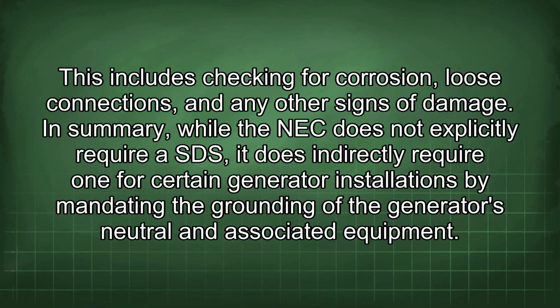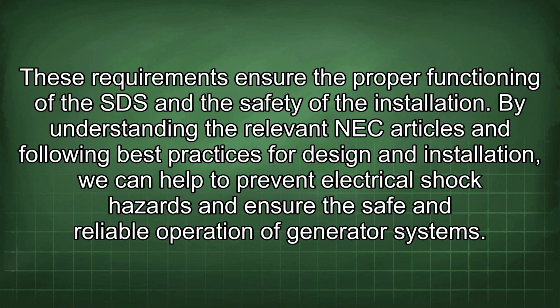In summary, while the NEC does not explicitly require SDS, it does indirectly require one for certain generator installations by mandating the grounding of the generator's neutral and associated equipment. These requirements ensure the proper functioning of the SDS and the safety of the installation. By understanding the relevant NEC articles and following best practices for design and installation, we can help to prevent electrical shock hazards and ensure the safe and reliable operation of generator systems.